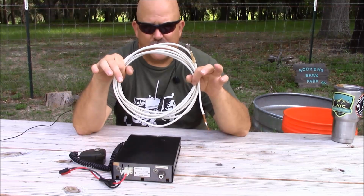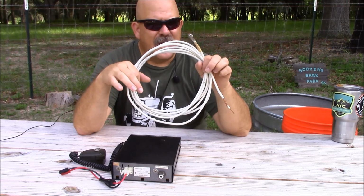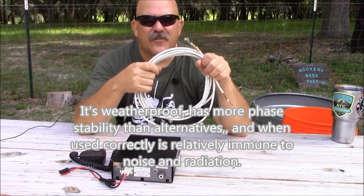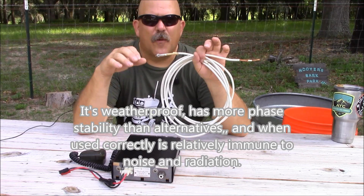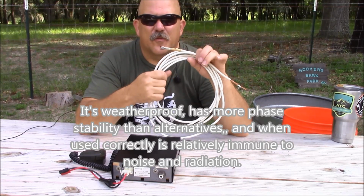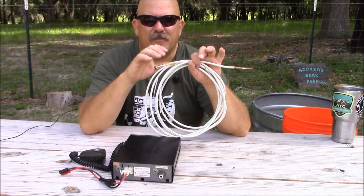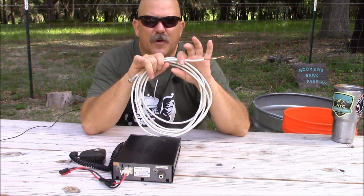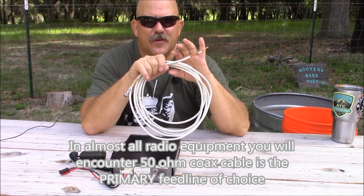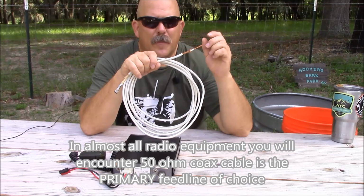We're often spoiled with the use of coaxial cable because it works so doggone well. It's flexible, it's easy to deploy, there's no real considerations for where or how you deploy coax cable. There's limits on length, of course, because there is a certain amount of loss that's inherent in the cable, and loss goes up as frequency increases. But overall, it's the most efficient solution that we have to use on field deployable radio frequency equipment.